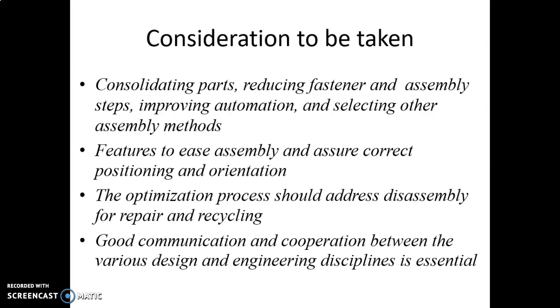Within the constraints of good molding practice and practical mold construction, we must look for opportunities to reduce the number of parts in an assembly through part consolidation.